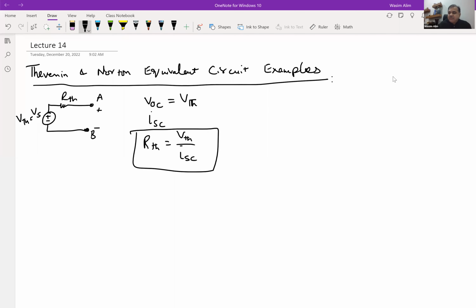And also, of course, you have the delta and Y models of resistances, which help you find any quantity. You can interchangeably translate between delta and Y circuits if you find that none of the resistors are in series or parallel. Once you convert from one form to the other, you will have a starting point, and then you can further simplify your circuit.